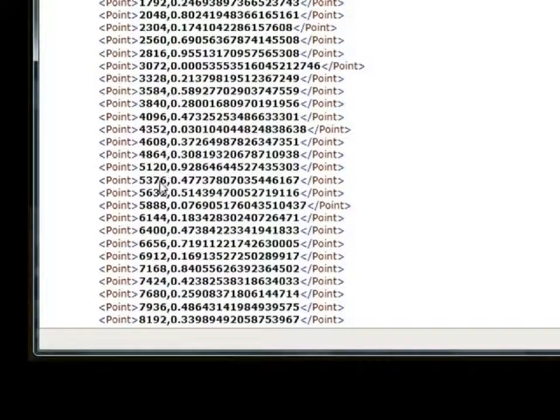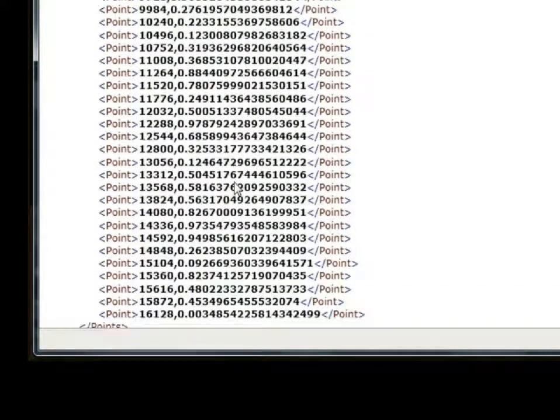You just have a proportional thing here. For example, 8-bit samples are made of values that range from 0 to 255. So you simply have to convert this 8-bit data into floating point data values. This is where all the trick is.